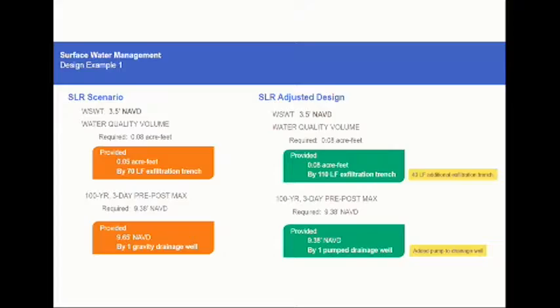So how do we fix that? Well, one of the things that we could do is if you look at this site, it was really close. All we had to do is add 40 feet of trench, which back when I used to do drainage design calcs, it was about $10,000 for 100 feet of trench.